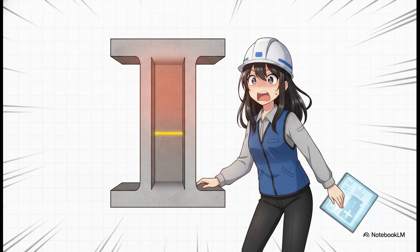But remember our girder dimensions? Our flange thickness is only 150 millimeters. 528 is much, much larger than 150. Our assumption was completely wrong. The neutral axis doesn't sit neatly in the top flange. It actually falls deep down into the web.